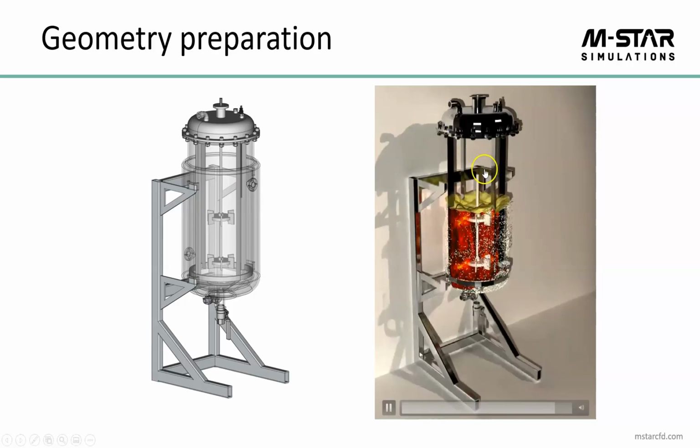We predict the time evolution of the torque on the impeller. We put a probe here to measure the time evolution of the velocity. We throw in dye or particles to characterize the blend time. We can use visual inspection to characterize the depth of the vortex. We corroborate the tool and use it in the same way you'd use and corroborate experimental data. That apples to apples comparison makes validation very straightforward. People see these digital twins and they know exactly what is going on because they're seeing the equipment they see in their lab, plant, and at production scale.